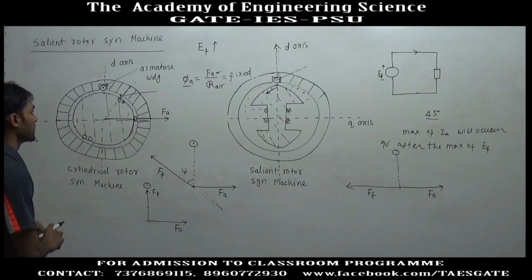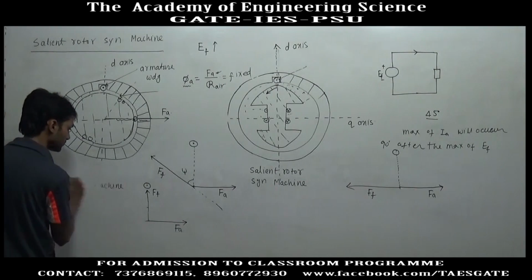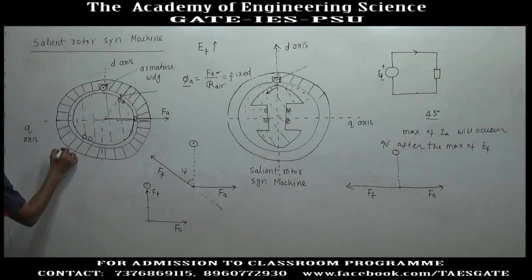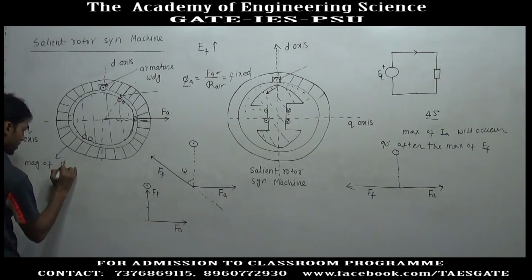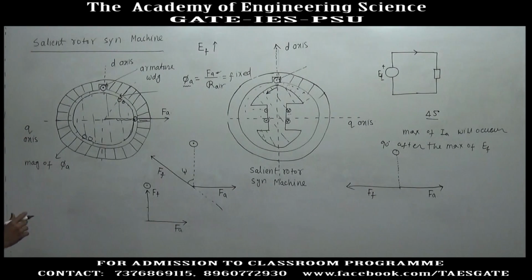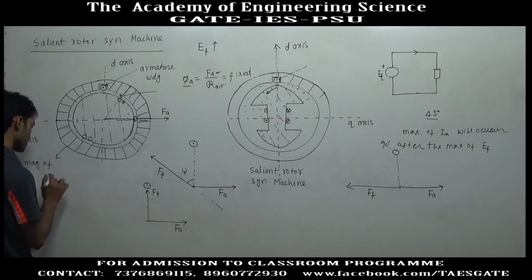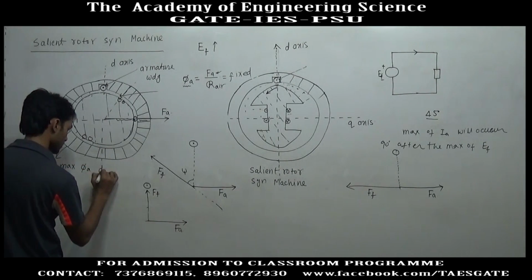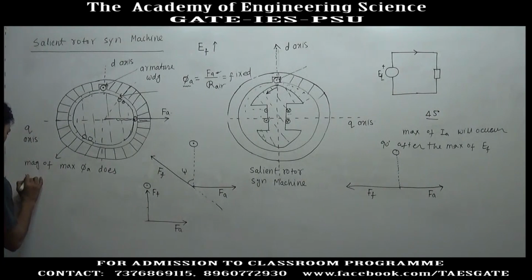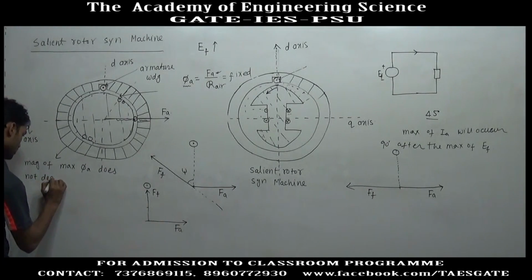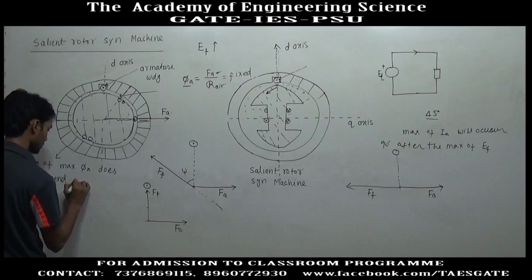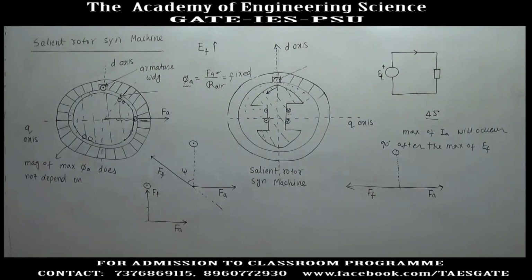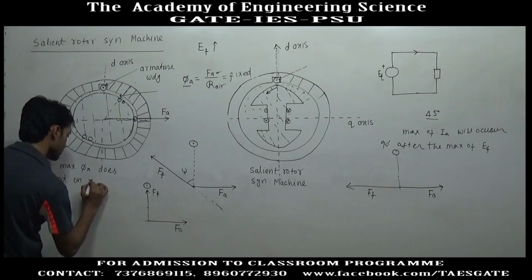I will write a statement here. In a cylindrical machine, the magnitude of armature flux, or the magnitude of maximum armature flux, maximum phi A, does not depend upon rotor position.